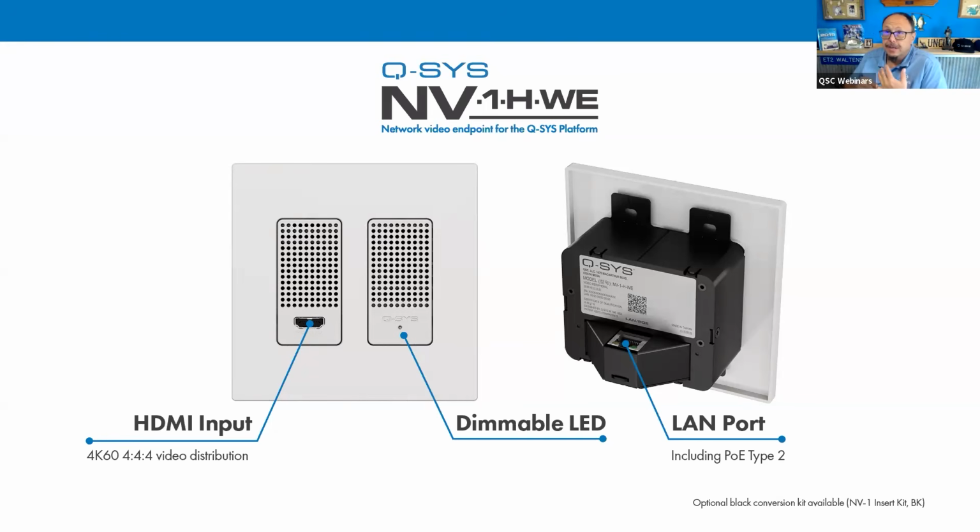Wall encoder that is purposefully named. If you look at the specifications and you read about this, for dissipation of heat, we're suggesting that it only be installed in a wall, right? Because if you start putting it into a floor box and you put a lid over that floor box, it could build up heat and all that. So we are rating it only to be a wall type enclosure with access for air to flow through these inputs on there as well.